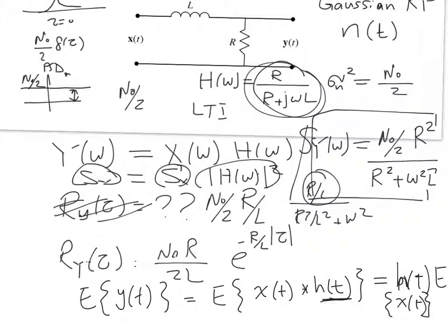The expectation is taking the expectation of whatever is random inside, right? The convolution is a linear process, integration and multiplication, so all the operations there are linear, and it also involves some time shifting. To avoid confusion, even though time shifting is not going to change the mean, assume that you are shifting the h and fixing the x, because in convolution you shift one and fix the other.